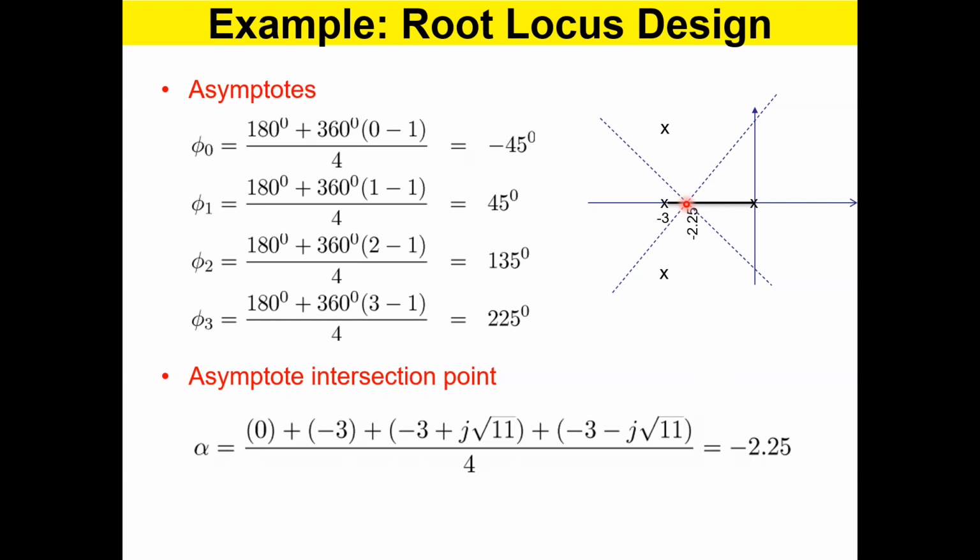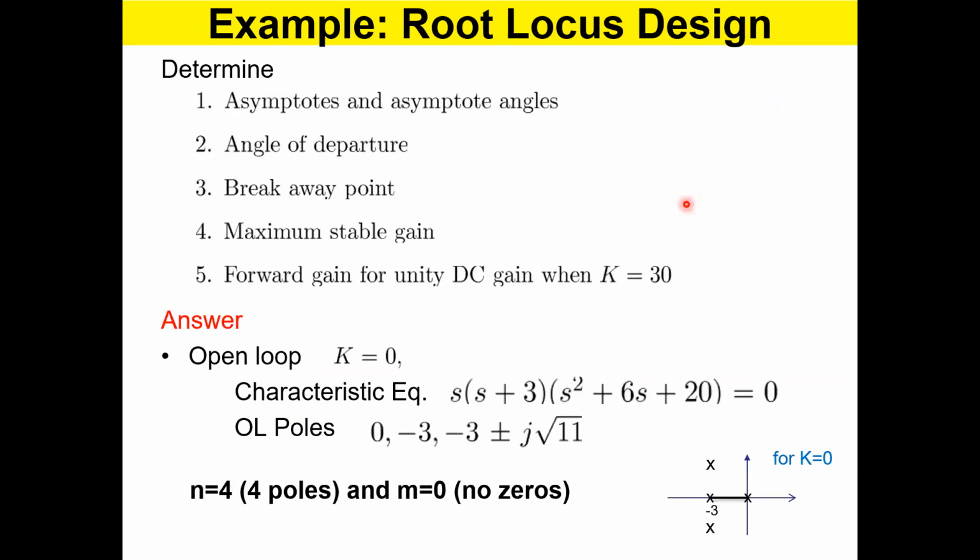Right. So now we gradually, this is like completing a painting, right? You draw the lines, arcs, points, and gradually you are getting to completing this root locus, right? Actually, I forgot one thing. It's pretty straightforward. Right over here, I just forgot one thing. When you draw the poles and zeros on the axis, you can see these poles, four poles, and there are no zeros. So altogether four poles.